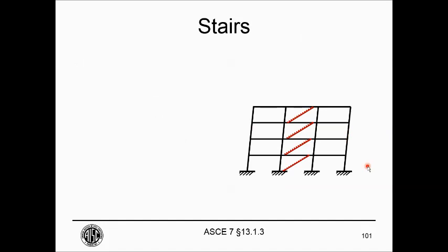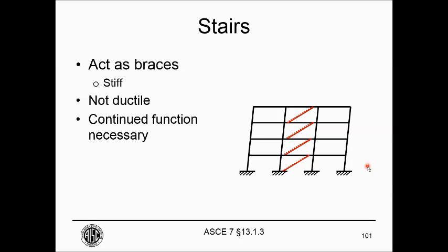One important aspect of design that sometimes has led to damage is very stiff elements such as stairs. Stairs, if they're hard connected, can tend to want to act as braces. They're very stiff, and they can be pretty non-ductile. Also importantly, after the earthquake, this is how people want to get out of the building. They want to use the stairs to get out, so their continued function is necessary.